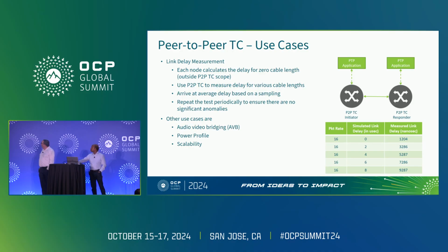It's also important to remember that I don't need the nodes to be synchronized to anything. I don't need the sync flow. I don't need any kind of master present to achieve that kind of accuracy. The nodes have very cheap Ethernet class oscillators, and we're still able to achieve these accuracies without any master or sync flow in the system.